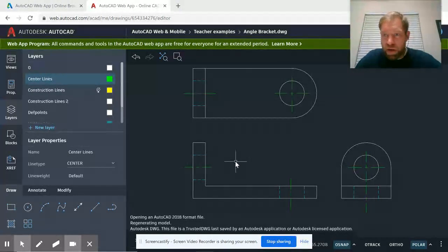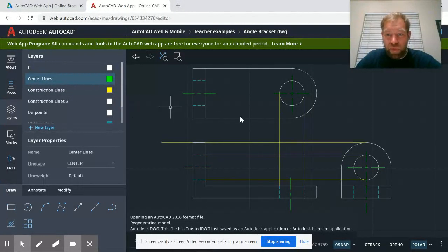And something of note here: in the first couple of weeks of our course, we practiced with the basic geometric shapes. We practiced with the line command. We showed you guys how to create arcs, circles, and offsets. But now I want to show you how to set up layers, because if you know how to set up layers, it can help you in your drawing. If I click on this layer called construction lines, it uses these construction lines as reference points that you can turn on and off.